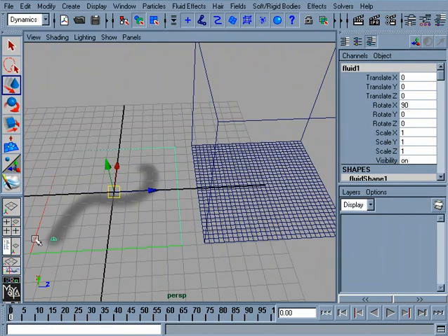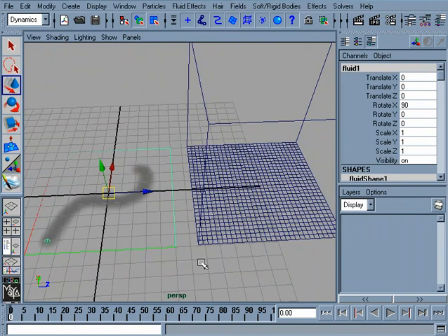So what we're pretty much going to do is write an expression that says if there is a certain amount of heat and a certain amount of density in this particular voxel, the one that's sitting right here, go ahead and ignite that corresponding voxel in this container. That's pretty much the basis of what this expression is going to be doing.